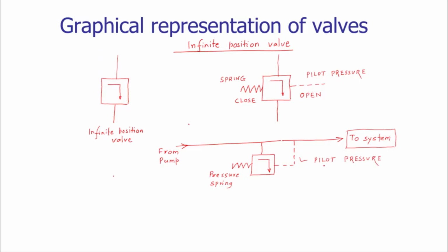Now when this pilot pressure is more than the cracking pressure of the valve, the valve will get open, and after opening up that valve, it will pass that excessive pressurized fluid to the tank or the sump.